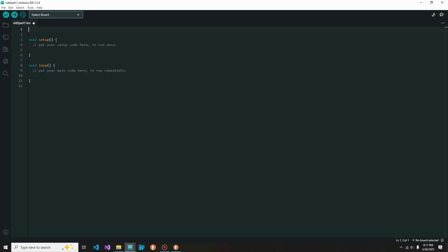So if you store any variables that aren't attached to pins, any kind of holding values that are put up there will hold on to that information and can be seen by other parts of the program that are further down the line. So we're going to enter in an int, an integer, and we're going to give it the name of LED, because we're messing with LEDs today, right? And it's going to equal, for us, or for you, pin 2.